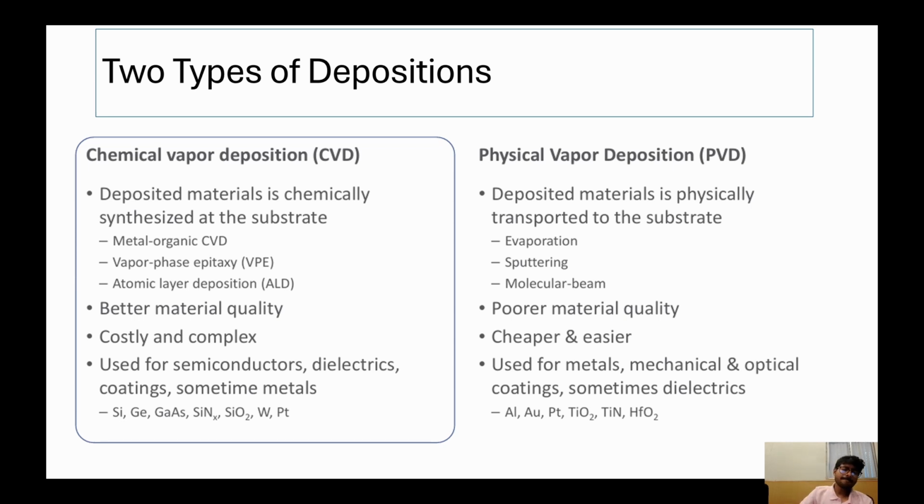On the other hand, chemical vapor deposition uses precursor gases that react at the substrate, and then the material gets deposited. For silicon dioxide we can use silane gas and oxygen. The silane gas will be converted into silicon, and that will react to form SiOH, and that SiOH will then convert into silicon dioxide. That we will see on the subsequent slides.